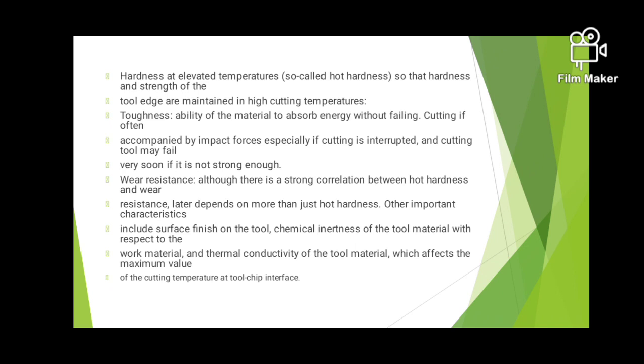Wear resistance. Although there is a strong correlation between the hot hardness and wear resistance, wear resistance later depends on more than just hardness. Other important characteristics include surface finish on the tool, chemical inertness of the tool material to the work material, and thermal conductivity of the material, which affects the maximum value of the cutting temperature at the tool chip interface.